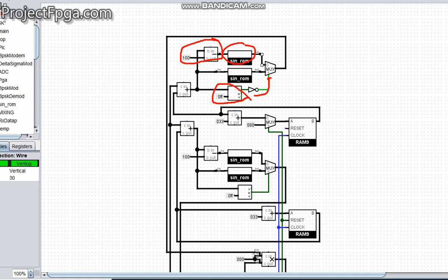So that's basically what happens up here. You can see this 0FF means 255. It checks if the value is less than or equal to 255, take it normally, pass it through the sine ROM and give us the output. Else, subtract 256 from it and pass it through the sine ROM. That was what was used to multiply our input ADC in.